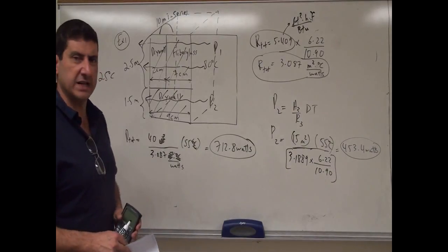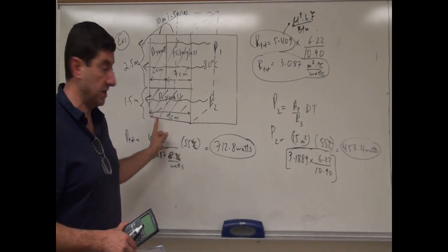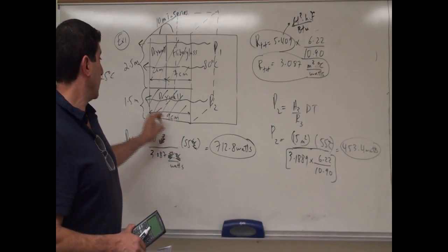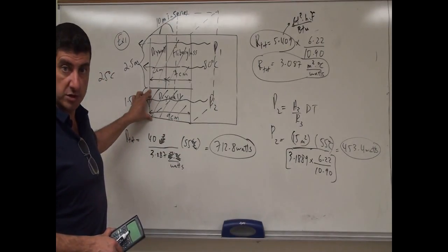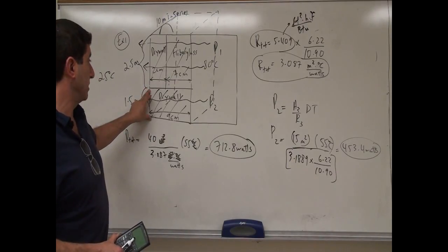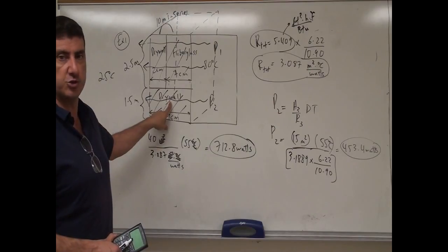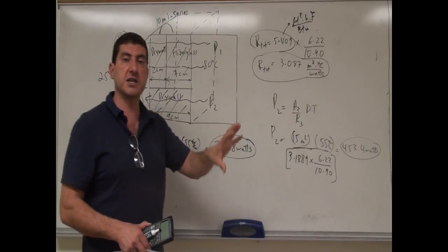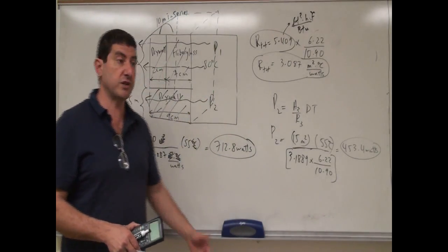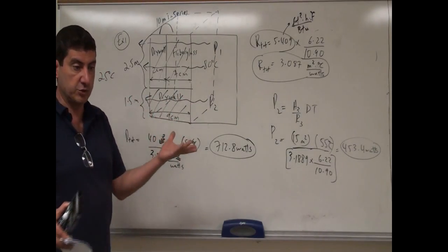Well, you see, that kind of makes sense because the bottom is dominating. Even though the bottom is thick, it's 9 centimeters, and even though its surface area is smaller, you would think that if its surface area is smaller, it should have less power loss. But the problem is that it's complete drywall, and drywall's insulation factor is very low. So most of the power is being lost through the bottom, you see. That's what happens when you have a house.